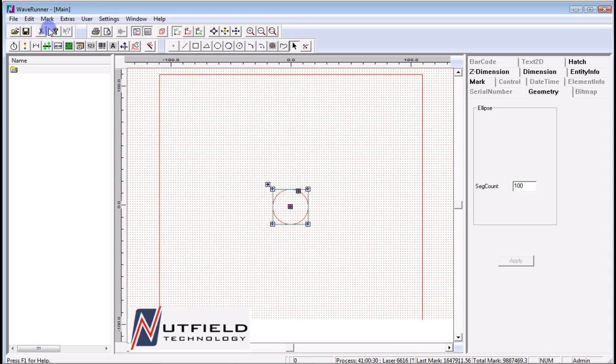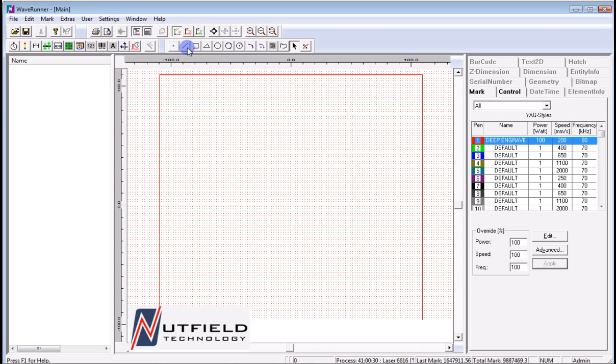The Geometry toolset allows the user to generate points, lines, rectangles, triangles, circles, arcs, and polylines. Each is created in a similar fashion by selecting the Geometric tool to use with a left click and then moving the mouse within the marking area of the View 2D space and left clicking once again to start the process.